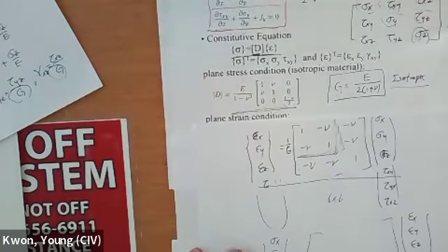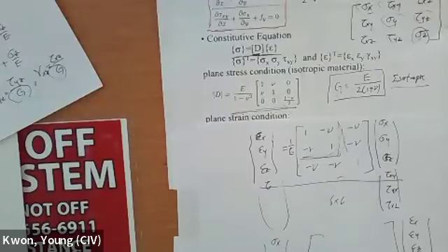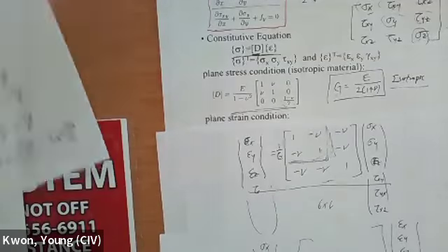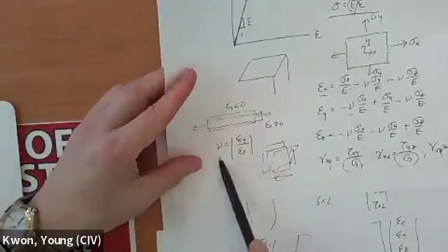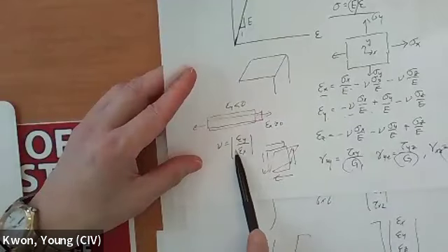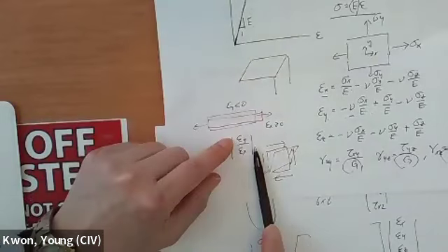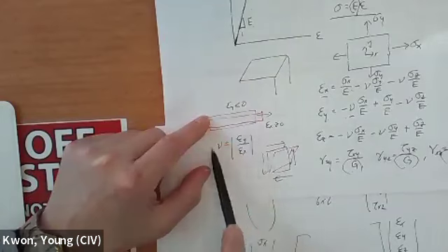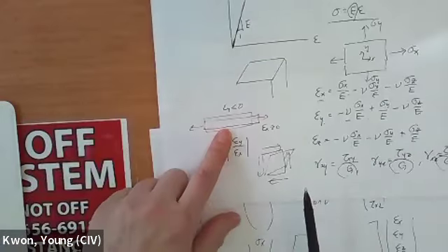So far, so good. Now, let me talk about one more thing, and then I'm going to just stop the discussion. What I said was that people define purposely that Poisson's ratio is going to be this way, absolute value. So epsilon y over minus epsilon x, and absolute value, that's the Poisson's ratio. Okay? And most material is going to be like that.